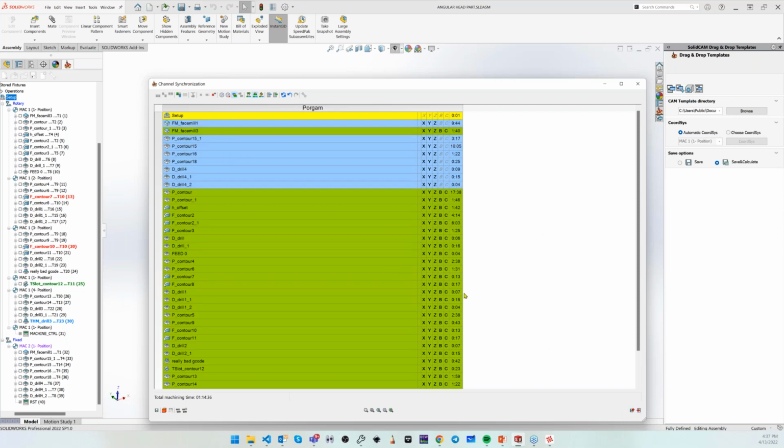Of course, we have webinars about channel synchronization, so I will not give it too much time. It's not complex. It's easy to manage. You see, it's done visually. And one of the strong things here is that you can take this part and move it to another machine that has only one table, and you don't need to change the technology. You will make the whole part in the first vise, make a new setup, and make the second part. The order of operations will not be changed. So it gives you the flexibility to work with different machines and different technologies.